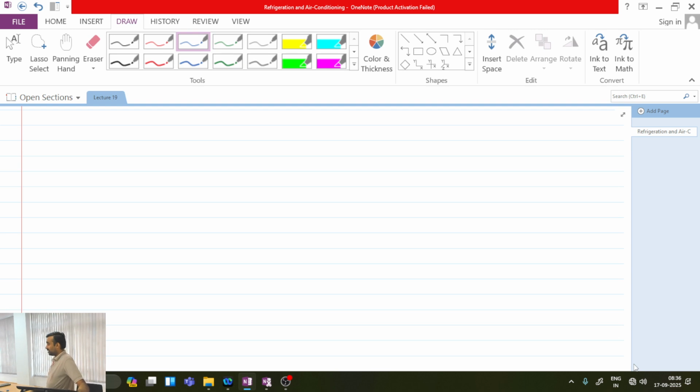But whenever I have a liquid mixture, which is a combination of A and B, if I have to define mixture properties in the superheated state, how many properties will be required? 3, because one more property should come into picture, which should define the composition of the mixture. So composition of the mixture will be coming as an additional property.